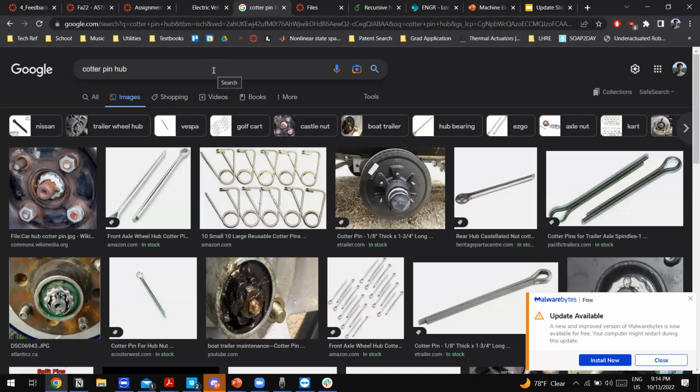Oh, the pitch. So pitches typically come for a given radius. They come in like 2 sizes, coarse and fine, and you'll see this referred to as UNC and I think UNF. Is that it? I don't know. But there's typically just like 2 thread sizes per radius. And honestly, it just depends. If you want better load distribution, you would choose the finer threads. But if you don't want to have to spin your fastener a million times, then you choose the coarser thread. You remember the thing where I said the bottom threads are loaded much more heavily than the top threads? It's exactly that. If you have a lot of fine threads on the bottom, they'll be able to distribute that pressure better as opposed to just one large thread.